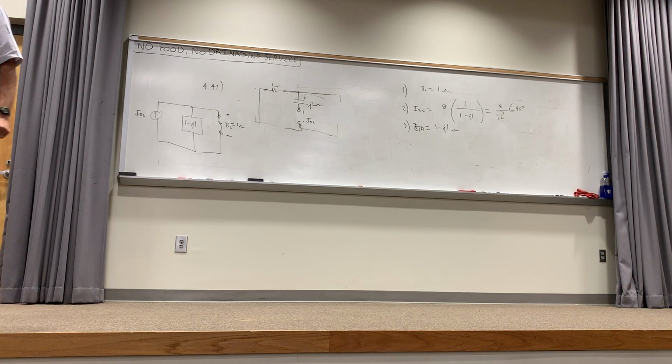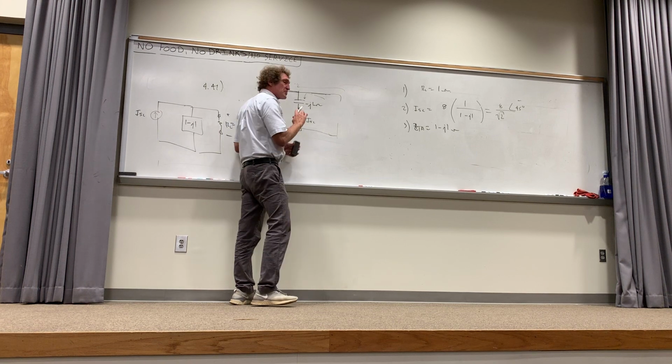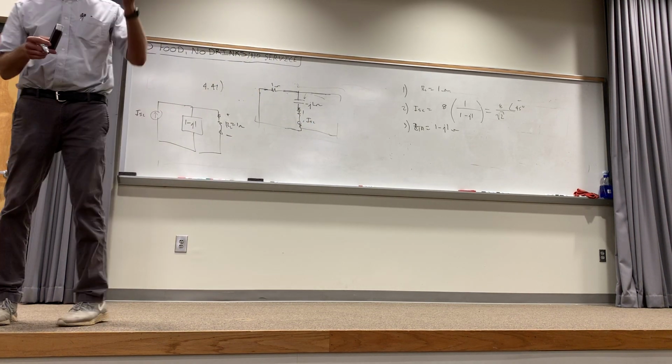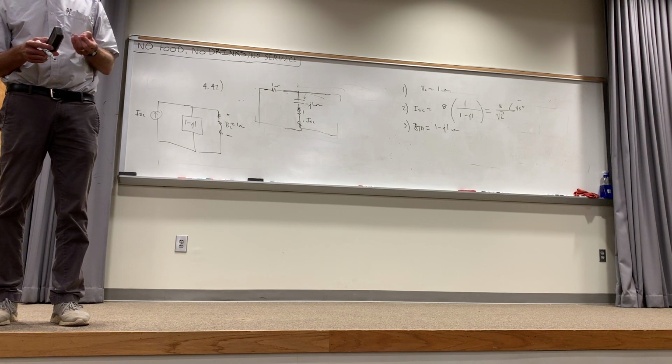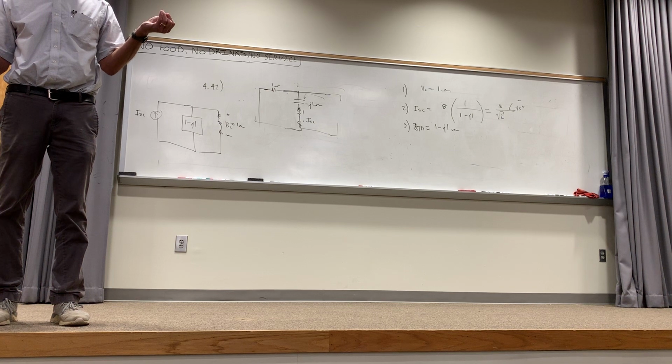Yes? If you were writing that circuit down and you used the wrong polarity for that resistor, would it show up as a negative voltage? Well, resistors don't have polarities. Resistors are just resistors. When you put a polarity in, it defines what you consider the positive versus the negative point of measurement. So you put them in, the resistors don't have that.